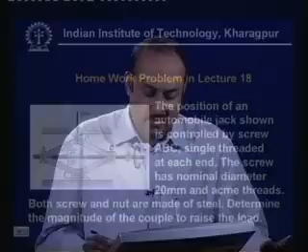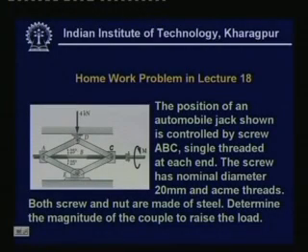Then comes the thread. The thread is very important, and we have to consider the bearing pressures in the thread as well as the shear stress in the thread as well as bending stress in the thread, and depending upon everything. So, combining all, we will have to find out the safe diameter that is used for the screw.